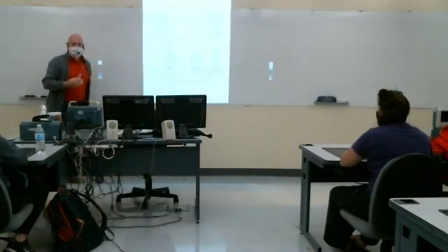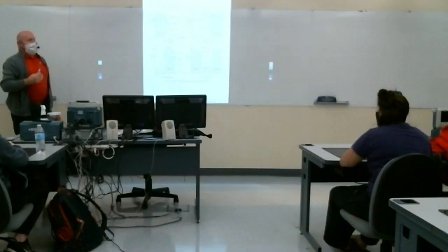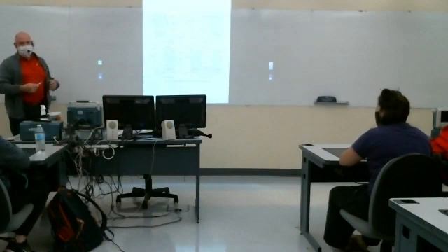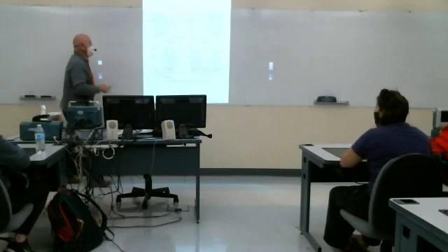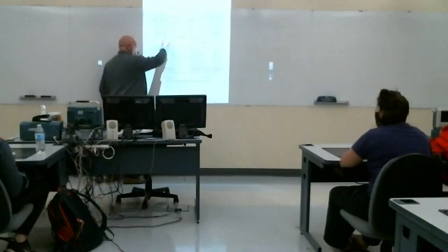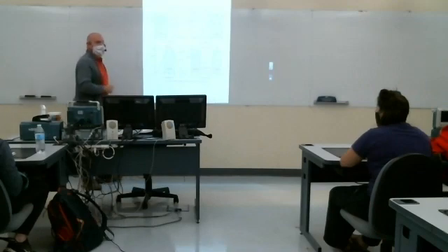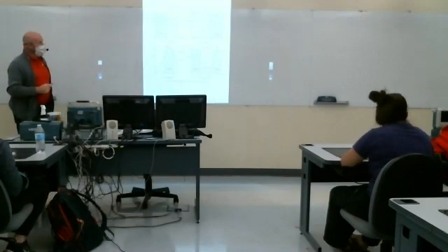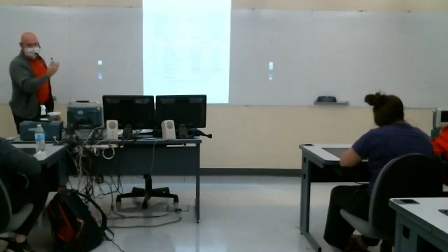It seems like an arbitrary thing. Why 1 over square root of 2? Why not 1/2 or whatever? 1 over square root of 2 in the amplitude response corresponds to 1/2 the power. So this is called the corner frequency, the cutoff frequency, the half power frequency. Those are all different names you'll hear applied to that corner frequency.